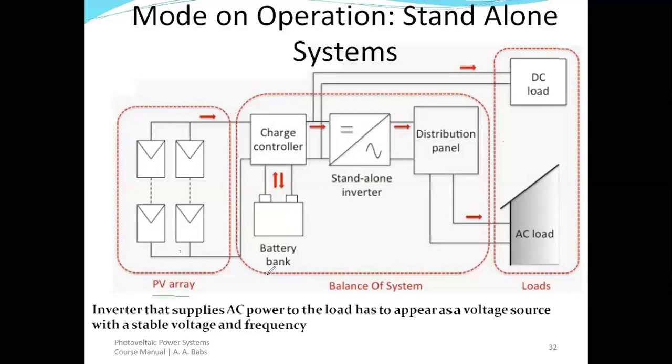If there is no sun, it simply means that no energy can come in, except we have a storage facility. And that is why all standalone systems usually have a battery bank, if you must keep providing power from your PV when the sun is not shining. The battery bank stores electrical charge. We have the charge controller here that ensures that all the circuit parameters are respected, and it also ensures that the battery is not overdrawn or overcharged.